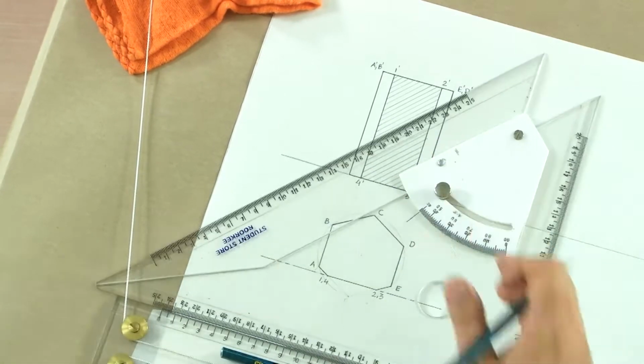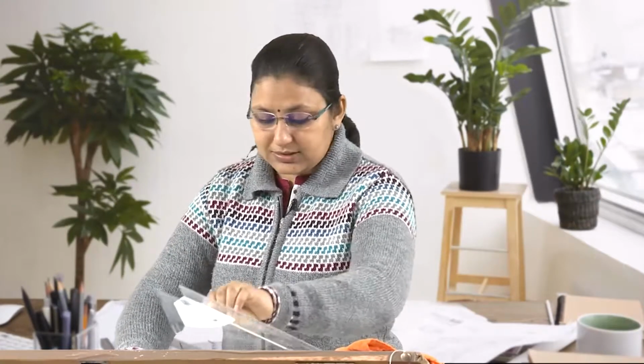Let's assume a triangular prism. In this lecture we are only looking at the prisms. So let's assume that we have an equilateral triangular prism which is kept on one of its faces. It is resting in HP on one of its faces, and the axis is inclined to VP. So in case we have a prism like that, what would we see? We will be actually seeing a rectangle from top and a rectangle from front with two triangles being visible. So that is what we will draw here.